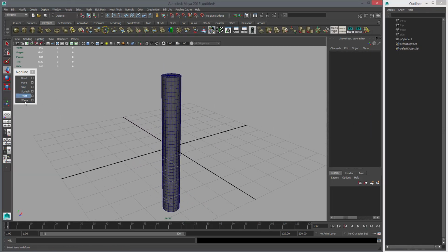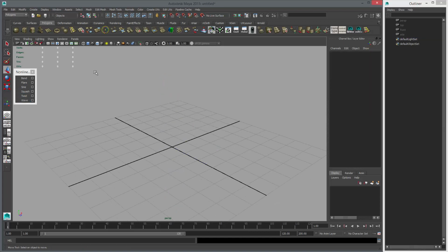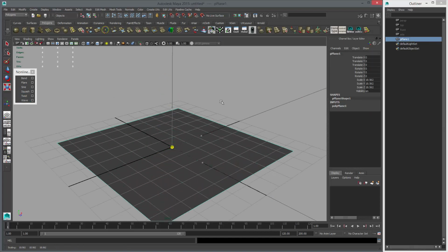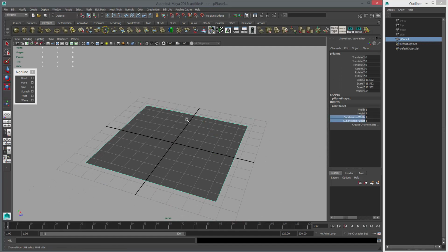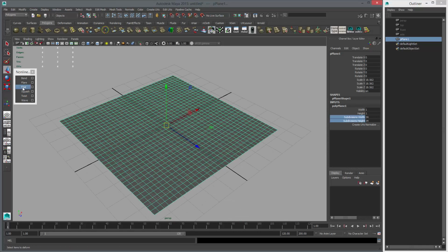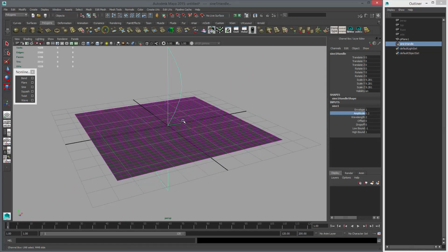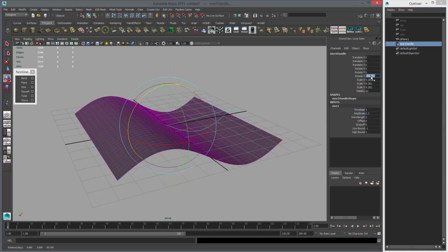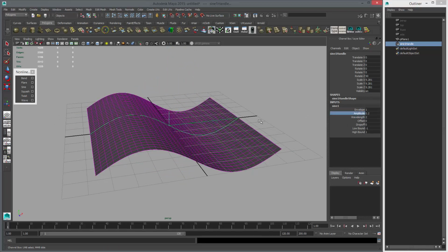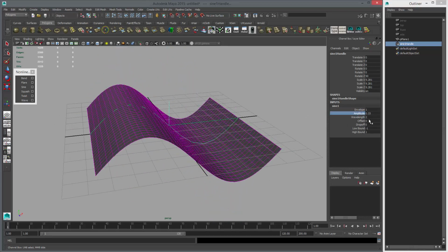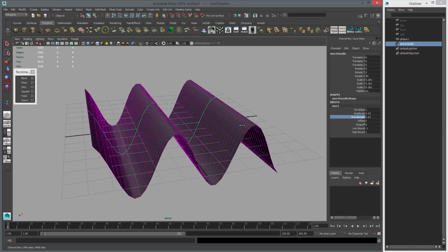And then I'll show you sine and wave, because those can't work on a cylinder. You need a plane to create those, or you need a larger object. It's hard to see it on a non-flat object. So if we grab the amplitude and change it, you see nothing really happens. That's because it's not rotated in the direction of the object. So if we rotate our sine 90 degrees, and then we change the amplitude, you can see we can change this object. We can increase the wavelength,